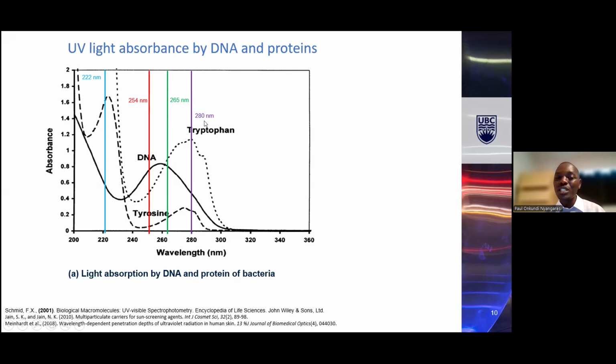Another factor we consider is what we have in the market and on the ground. I explained earlier there are challenges in fabricating the UV LEDs. I knew I'd get this question. One of the challenges is material quality. When you add aluminum, you are reducing the wavelength. So the lower the wavelength, the more aluminum you need to add, and the more aluminum you add, the poorer the quality of the material. So between UV LEDs of 265 and 280, you'll find the 280 is more powerful in terms of power. If you take two UV LEDs at the same cost, 280 outperforms 265 by far.